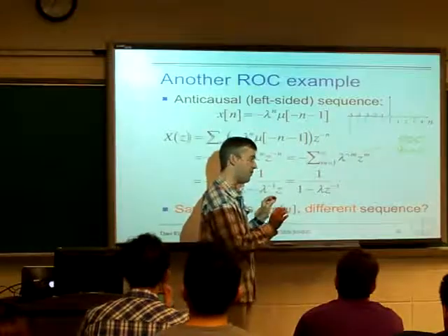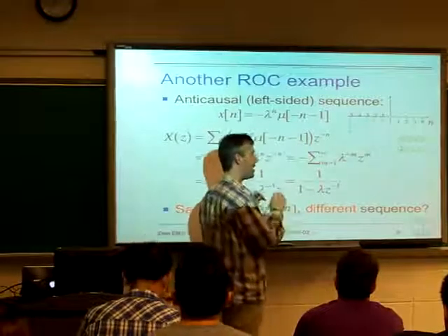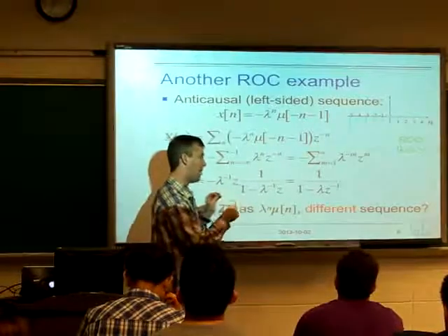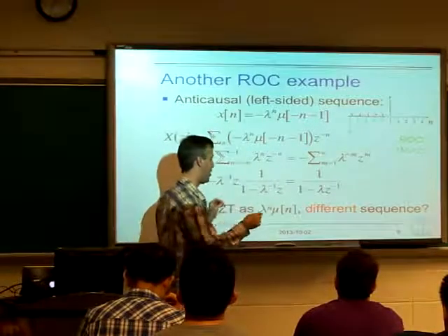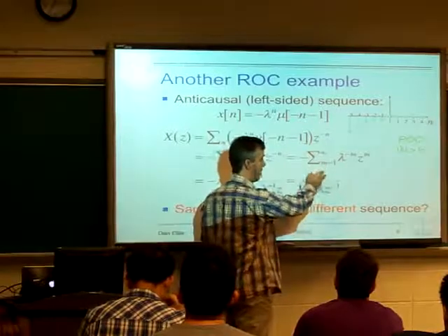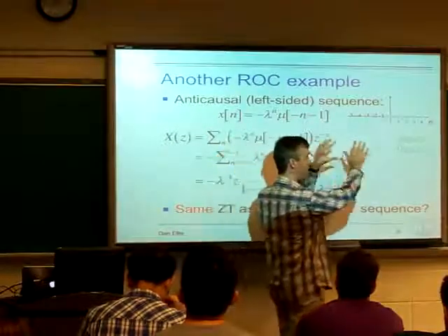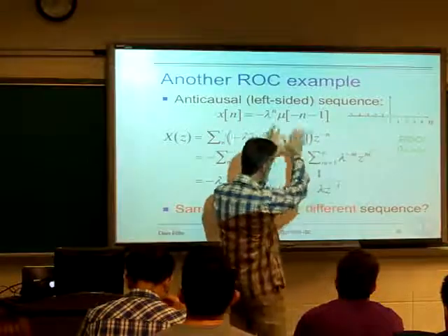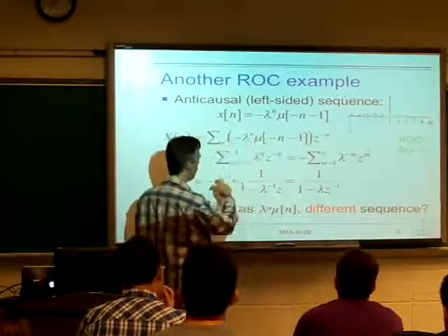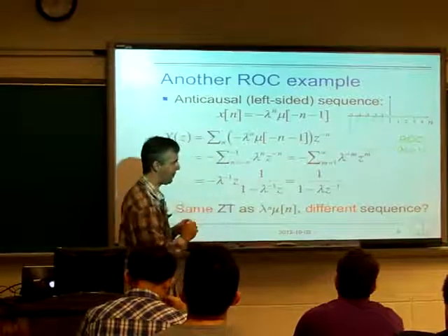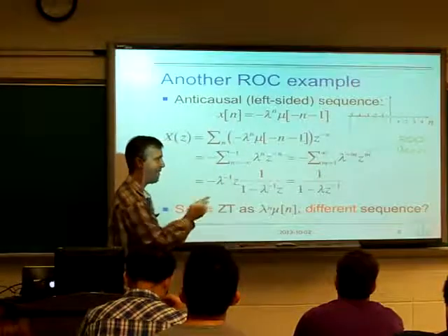Shifting it in time, as we're about to see, the z transform of a function that's shifted in time is just z to the minus n0 times that function. So if we just put some constant power of z on top of here, we get the z transform of a sequence that's shifted. And then you can see that's going to work out here. But yeah, we get different powers of z out here, and then it wouldn't be quite so neat. But yeah, it would look the same.